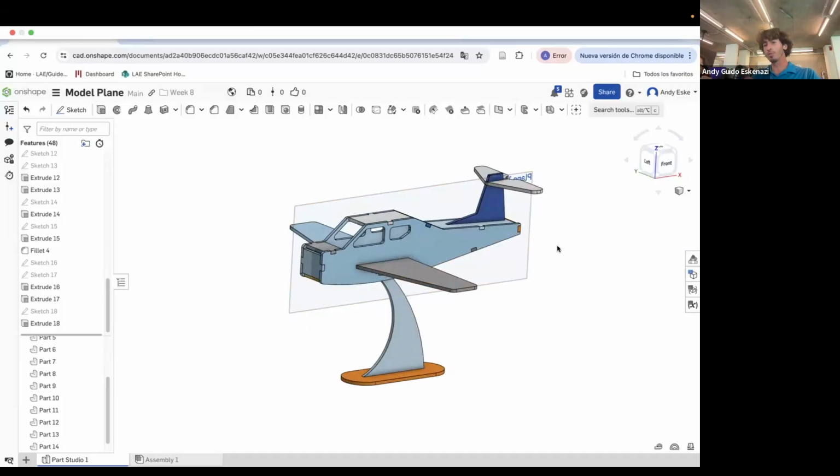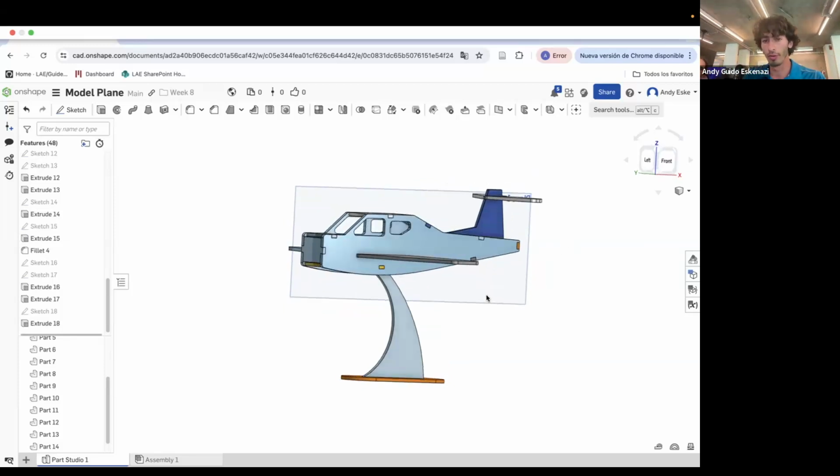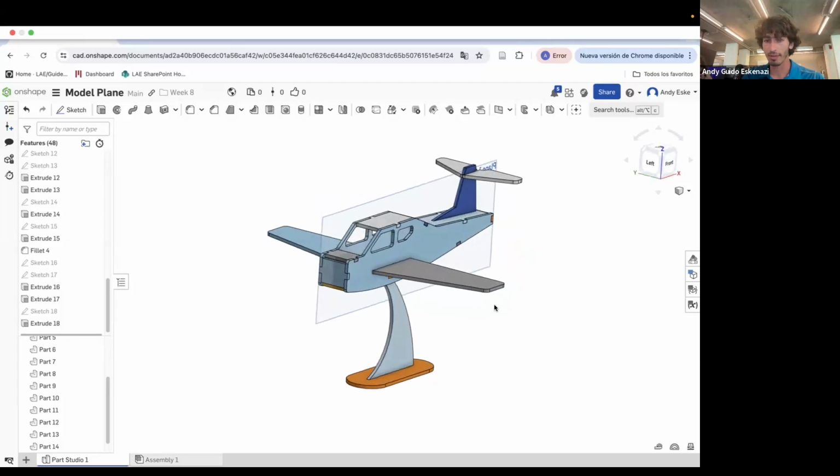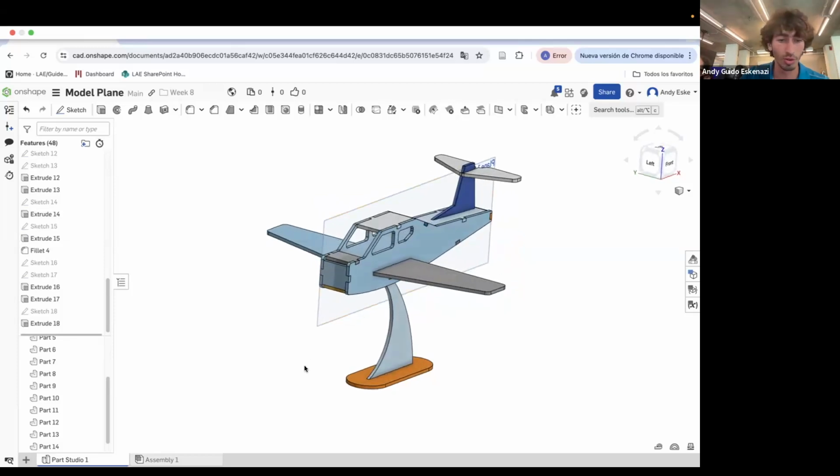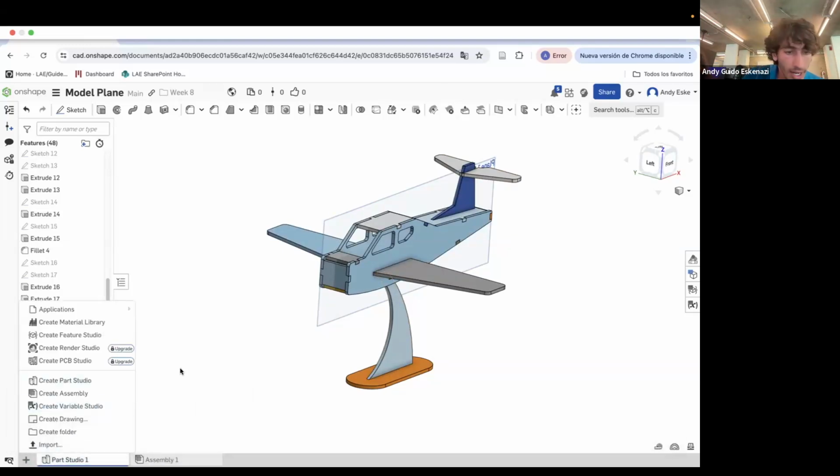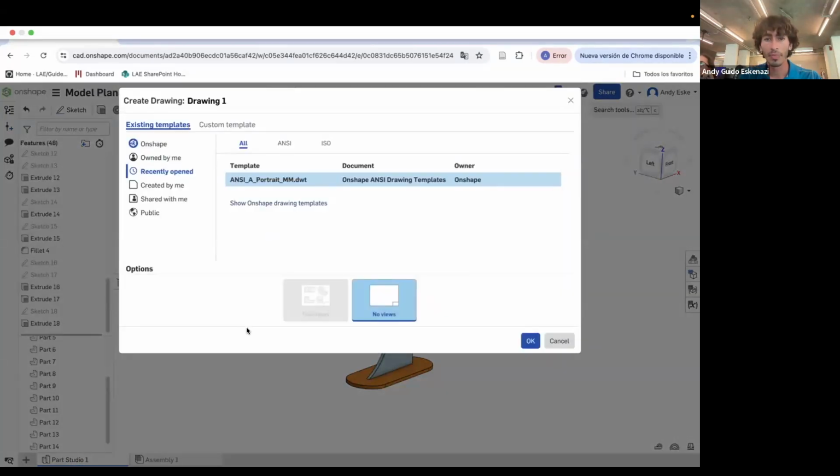So this is the fun part because I don't think we've done drawings yet. No, so today is the time to do it. So we'll make one where we're putting a picture of, actually, how about an idea? Let's go here to assembly. Where's the plus tab? You can click in there, and there is a tab that's called create drawing. So we'll create drawing, and we're going to choose ANSI portrait, the one that I like because it's vertical, and I'll say okay.